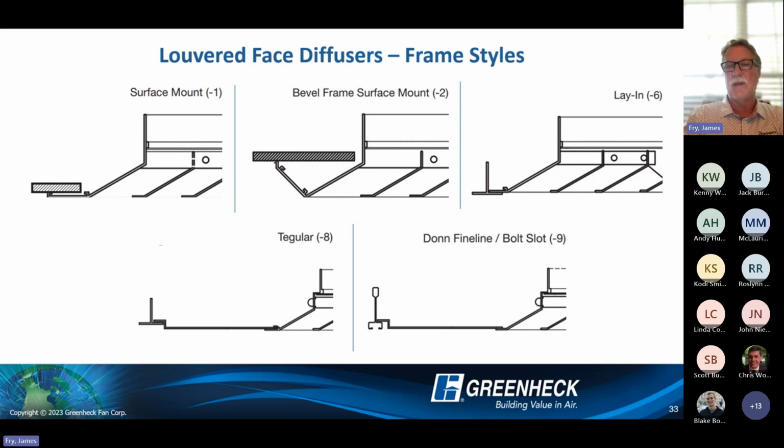you would not have to use a ceramic or thermal blanket to protect the exposed metal. Your radiation damper will cover enough. But if you use the frame one, you would have to add an additional cost and labor to install a radiation damper to protect that exposed metal.